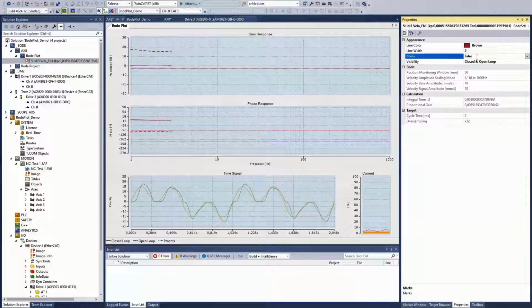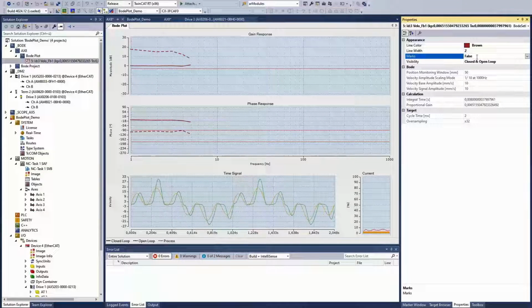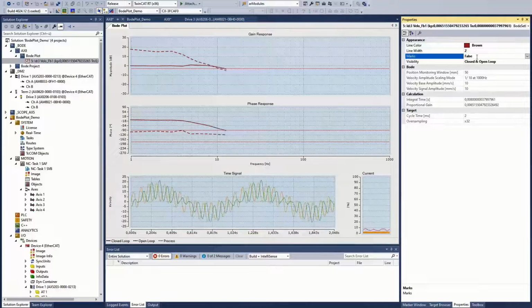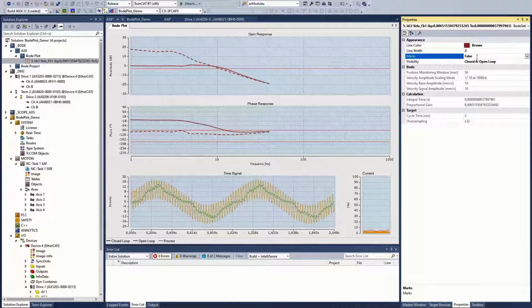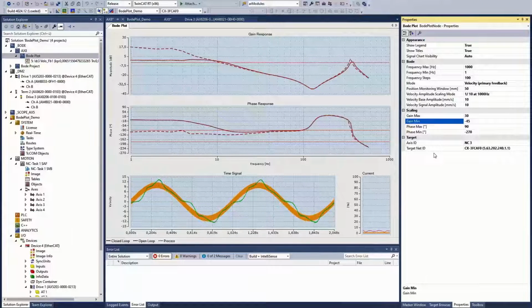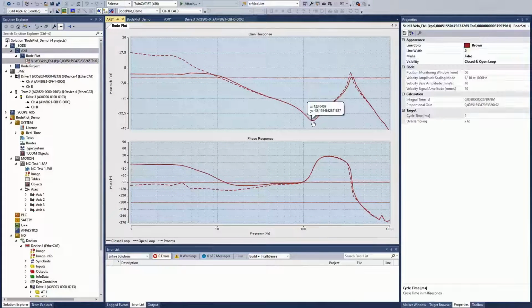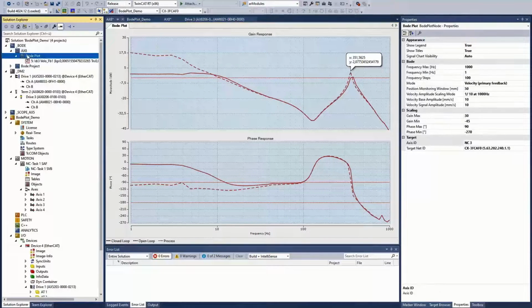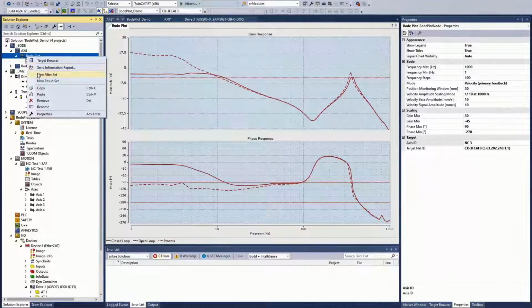So with default settings, we want to check the system. You see again, closed loop starting at 0 dB, but then when it's going to higher frequencies, it's going down, reaching a minimum, and then it's coming up again. This is something where we have an anti-resonance here at 130 Hertz, and we have a resonance at 351, 52. This is typical for a two-mass system.